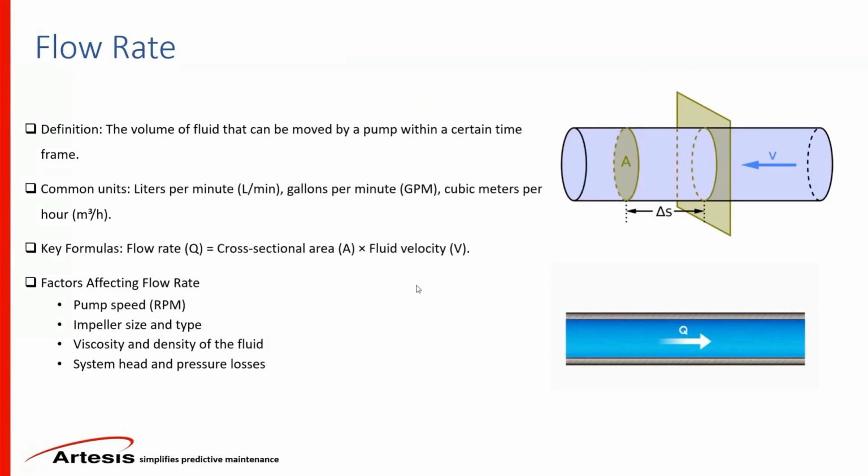So, the importance of a flow rate, of course, is that it is typically used in industries in different applications in order to determine the size of the impeller or the pump capacity. And without that, you don't have the ability to size your pump or, again, the impeller. So it is calculated by multiplying the cross-sectional area with the velocity of the fluid.